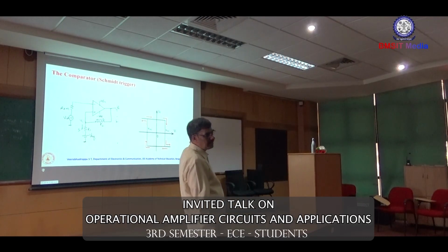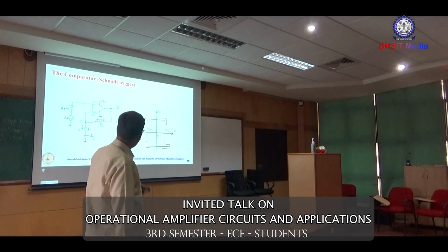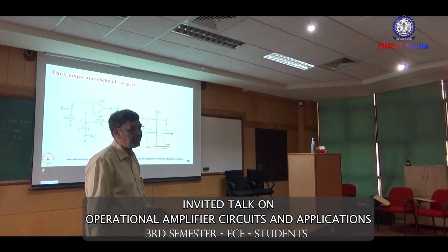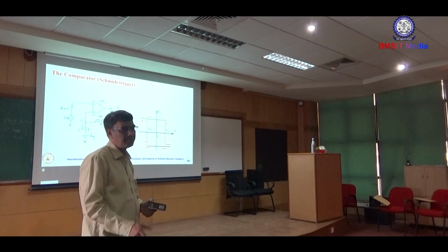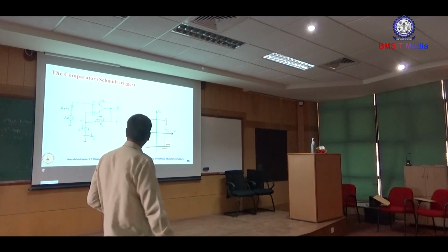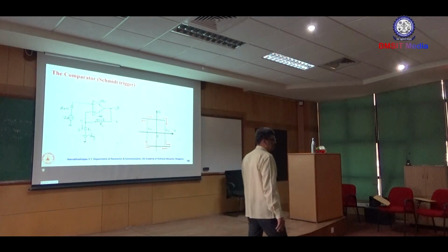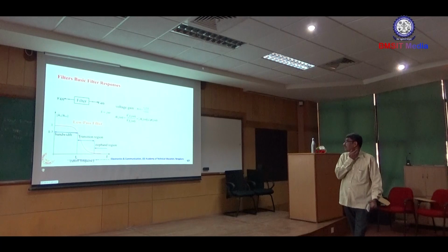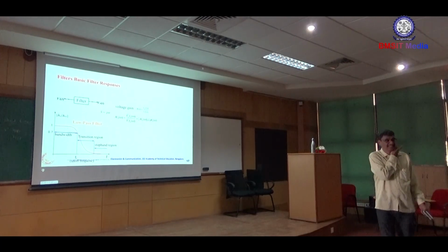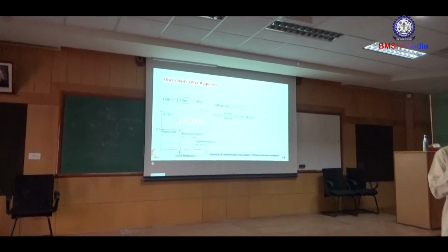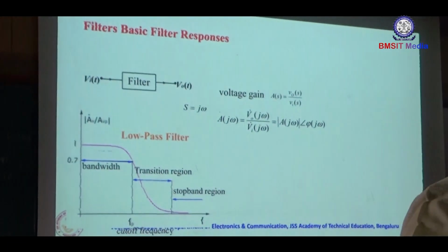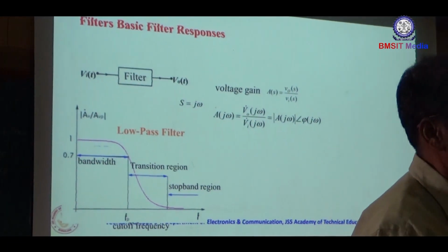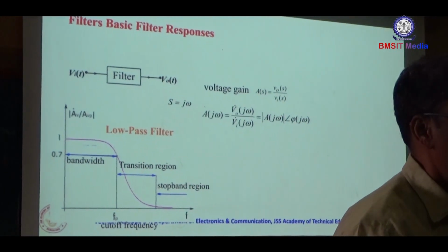Depending on that, you can also have one positive and the other negative, then you have to set that reference voltage or choose the proper resistance values R1 and R2, the way in which you design the Schmitt trigger. This is about the basic applications, what we have discussed till now: negative feedback amplifiers and, as part of that, positive feedback amplifiers.